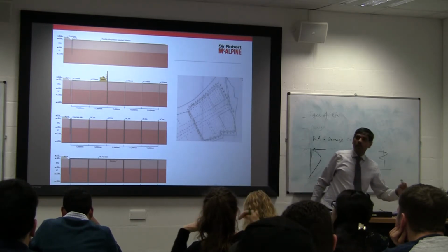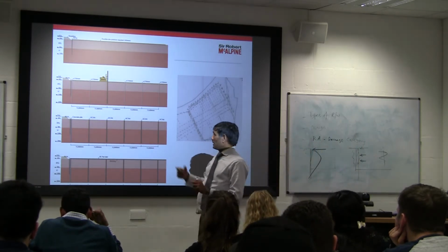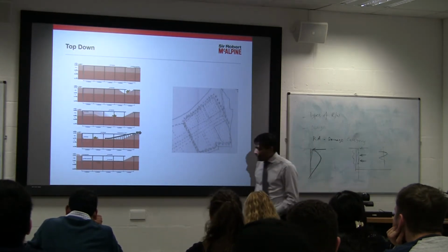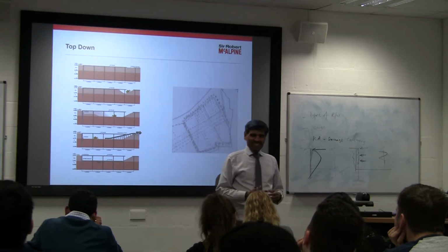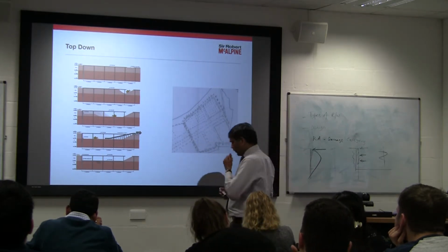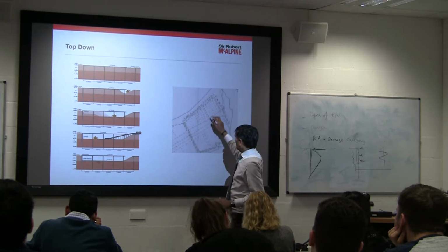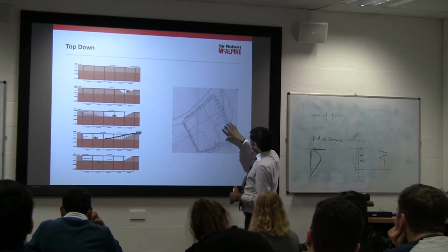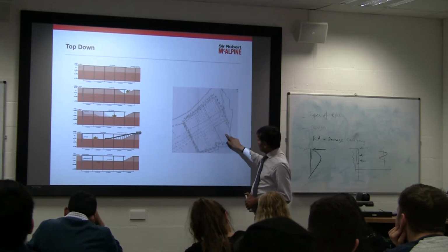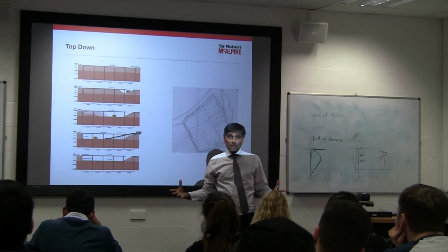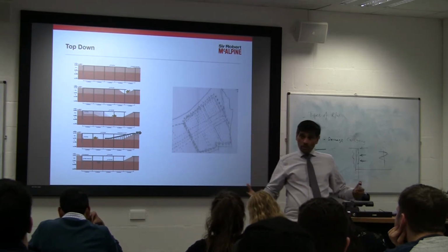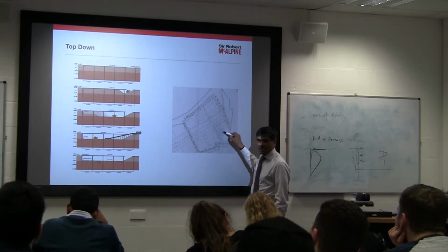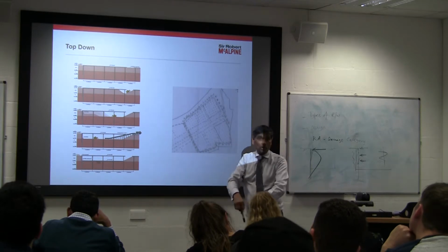How many gaps did you need to get on? Right, yeah, I'll come to that, yes, exactly. That's a very good question. So obviously, very important: what do we need to get the muck out? So normally, for any big space like that, you can compartmentalize it. If a team is working here, you want at least a 10 meter by 10 meter, what we call a muck hole. Yeah, muck hole. So obviously the stuff that is going to be dug, or whatever you're excavating, comes into the center of the site and then is taken out by a long reach excavator.